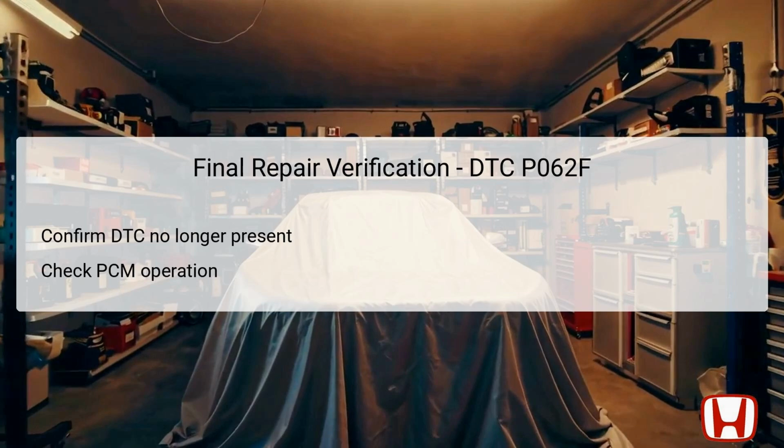Conduct a functionality test of the PCM, checking that it correctly retrieves and writes data to the KAM without interruption. Any recurring issues would indicate that further diagnostics are necessary. Verification is a critical step in the repair process, ensuring that any remedial action taken has been successful and that the vehicle is ready for safe operation.